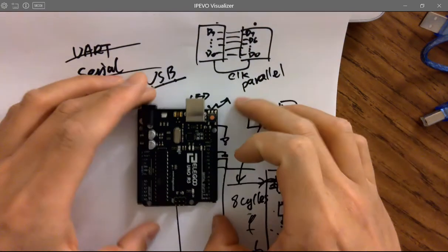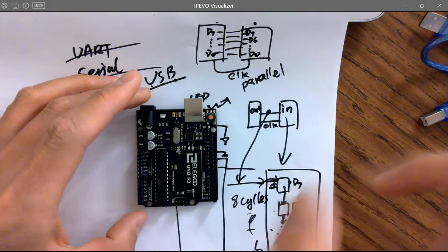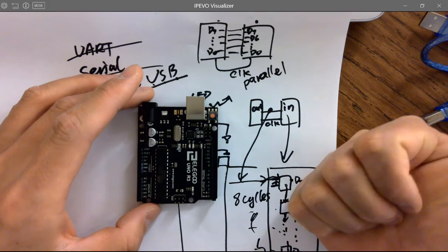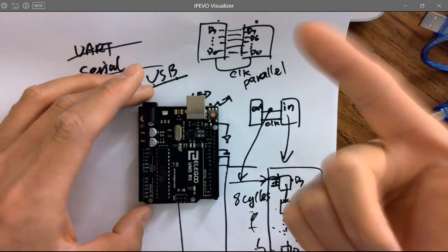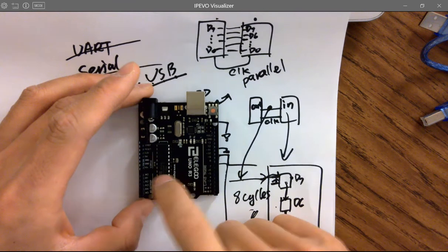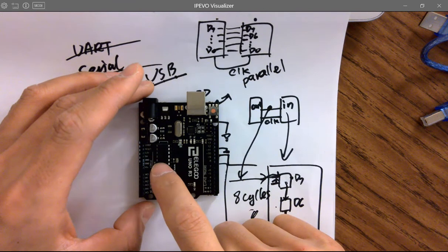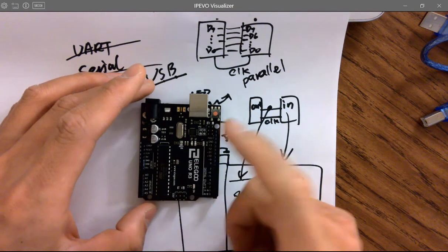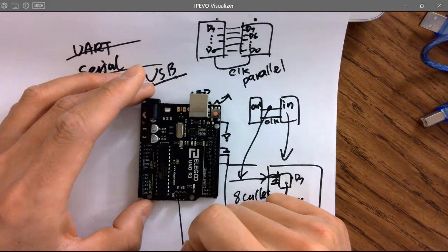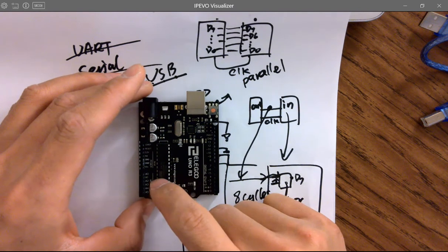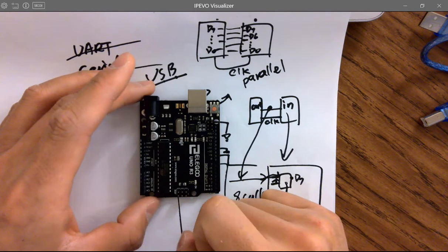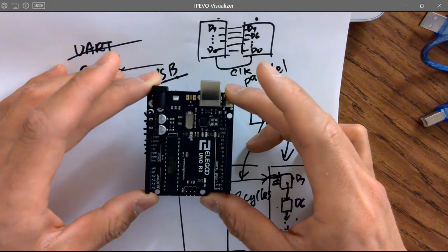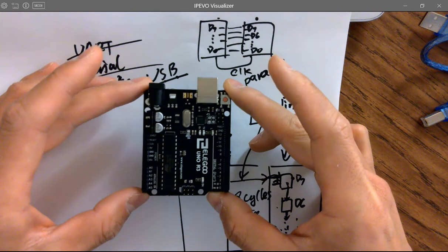FPGAs are different. So 2 reasons that FPGAs are faster than microcontrollers. First, you can do parallel computation internally. Second, usually the FPGAs are newer technology, unlike this one. This is 350 nanometer technology, very similar to the 500 nanometer technology, which was like 30-year-old technology we have been using. And I'm pretty sure they are manufacturing millions of these chips for this kit, for general purpose, for fun actually.